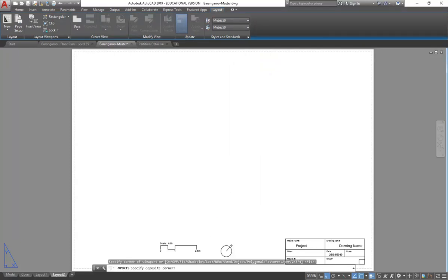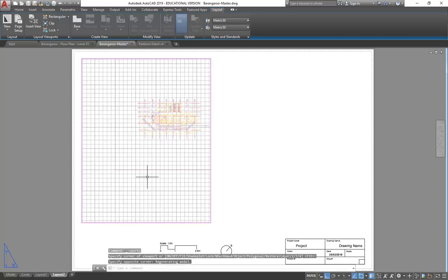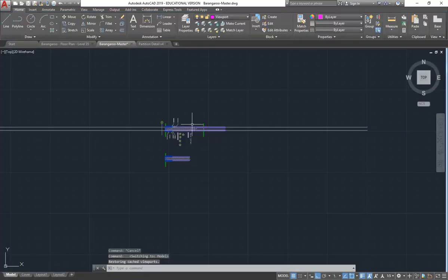And this is a really good tip. If you know that you need to rotate the view inside your viewport, always make a new viewport instead of copying another one, because there's a little bug. I'll show you what it is. I always just rotate it with model space on the layout, but then if you want to keep projecting back in the model tab, you'd have to rotate it back or do something else extra. So this just saves you a step.